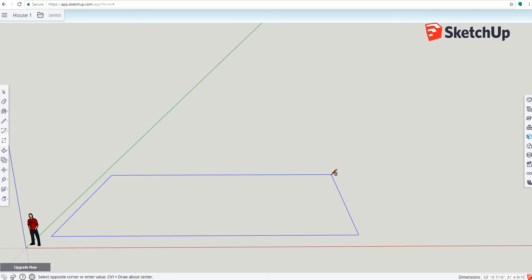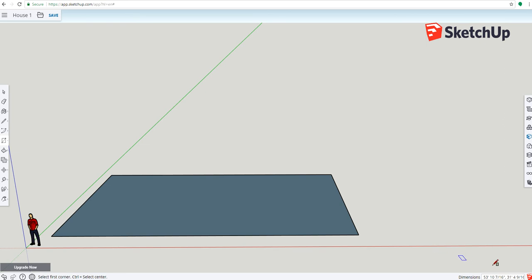What I'm trying to do is get in the dimensions box the first dimension around 50 feet, second dimension around 30 feet. And so I let go of the mouse, and once you see here, I have about 53 and 31. That's pretty good. If you don't quite get it, you can come down here and click undo. Or if something happens and you click somewhere else, or you're making a rectangle and you lose that dimension, here's what you can do.